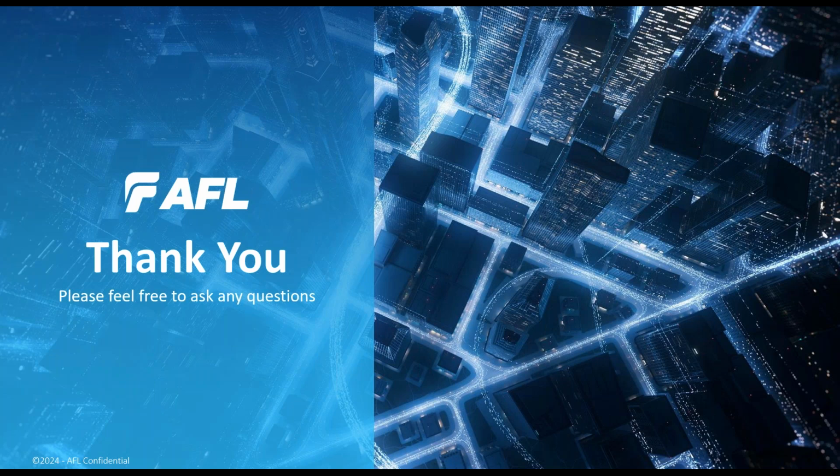Okay. Somebody asked, what is the difference between a micro bend and a macro bend that you referenced? Yeah, so macro bends are caused by external activity once you've installed the cable. And if you apply too tight a bend to that cable, you can introduce a macro bend. And depending on the fiber you're using, there's a recommended minimum bend radius.